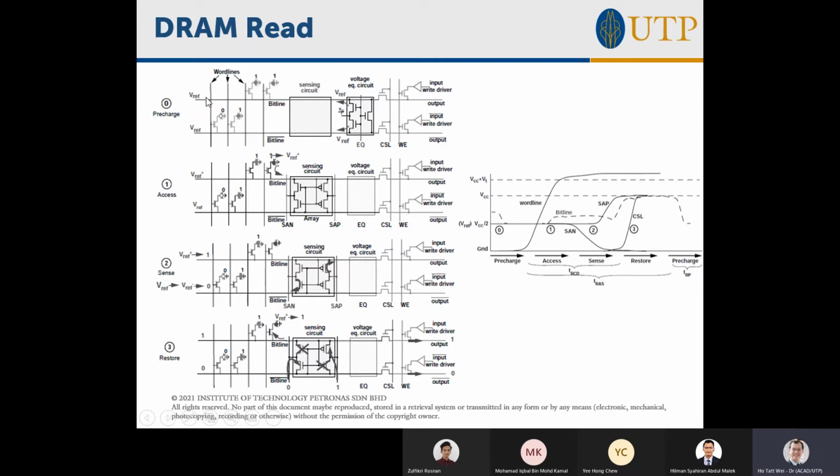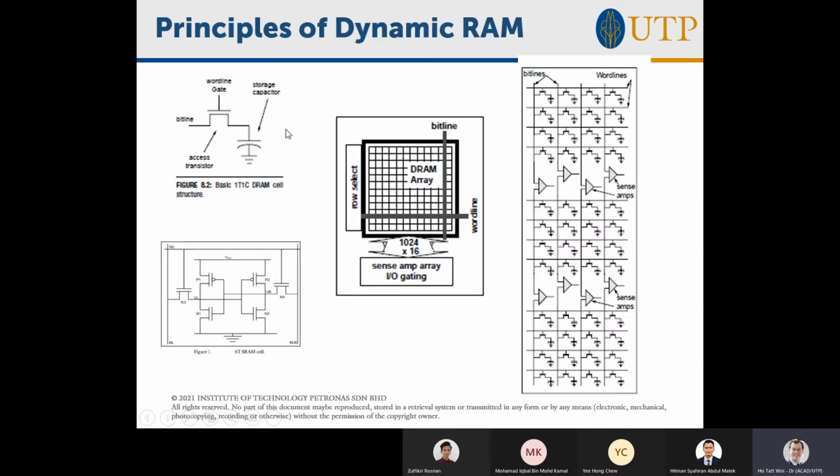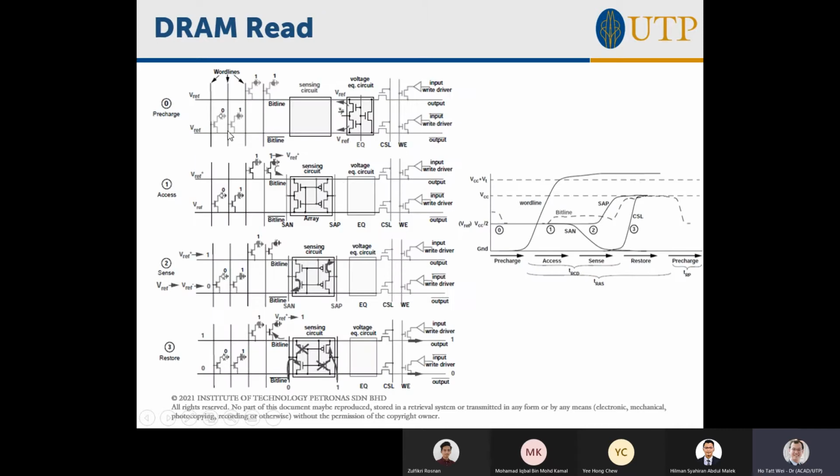Okay, 1 bit. Actually, there are 2 bit lines, a bit line and a bit line bar. They're always pairs of bit lines, taken together. So this bit line is paired with this bit line. One of these will be positive logic, one of these will be complementary. That means here logic 1 is logic 1, and here logic 1 is actually logic 0. And that's what's represented here.